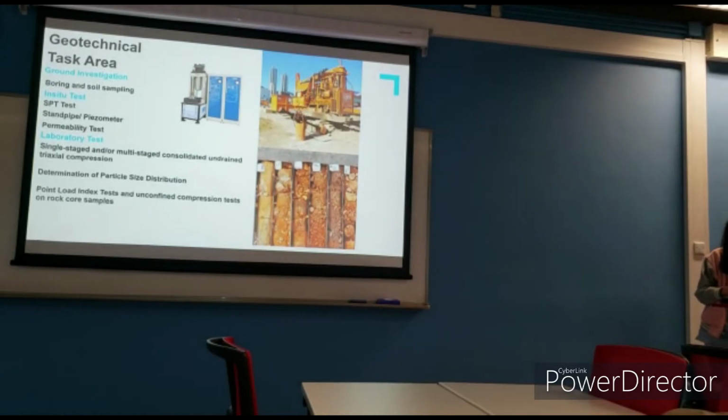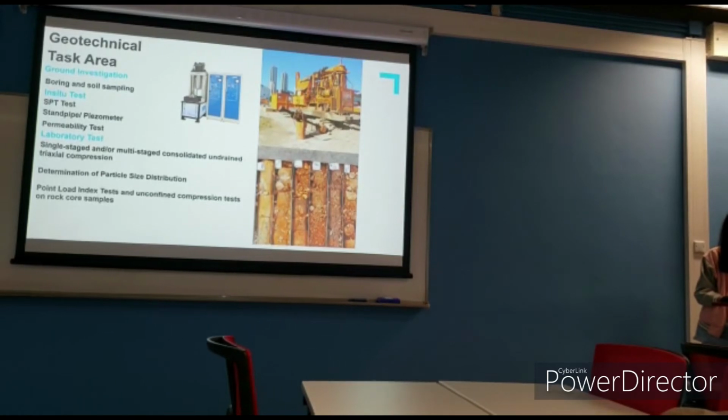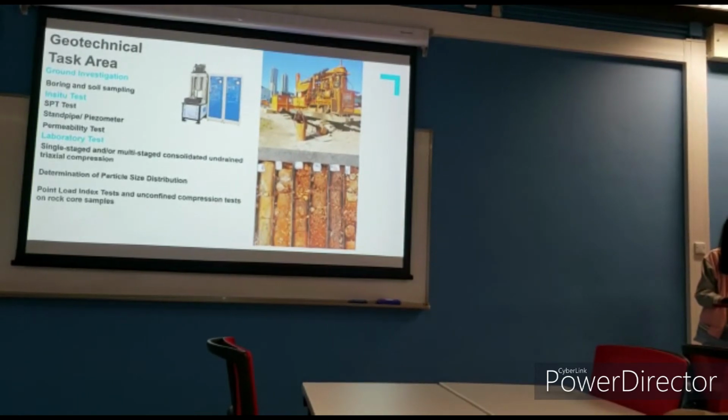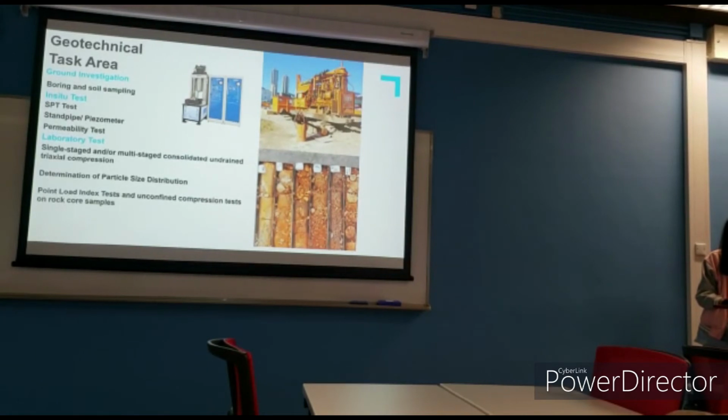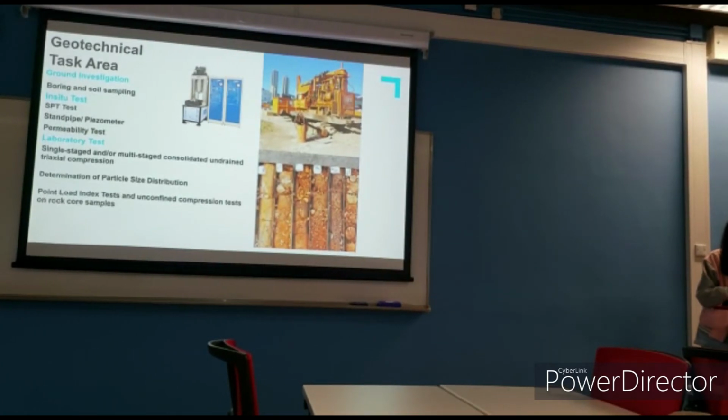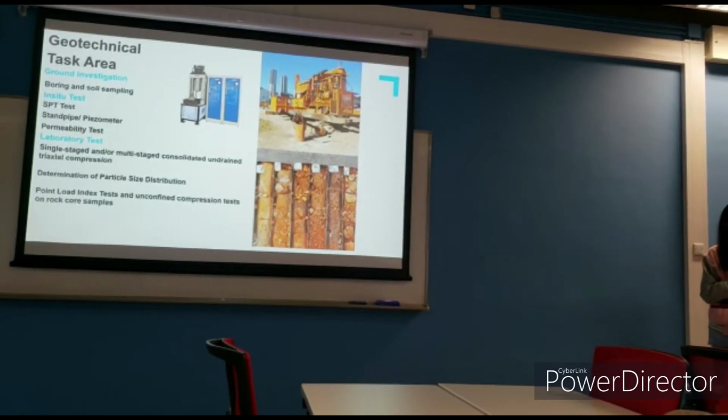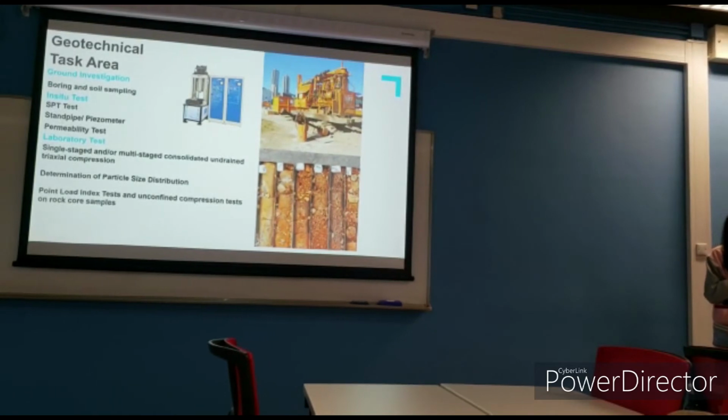In order to get the soil strength and other critical design parameters for the foundation works, we should carry out laboratory tests on the soil sample, including a single-stage or multi-stage triaxial test, determining particle size distribution, or a point load test to verify the rock and determine the soil or rock strength for the design purpose.